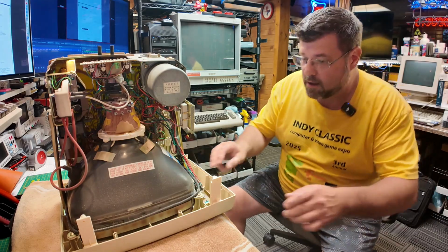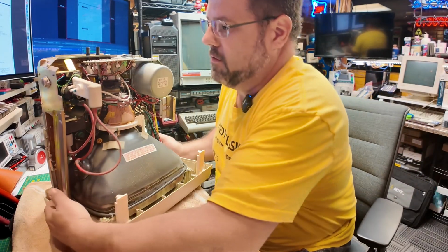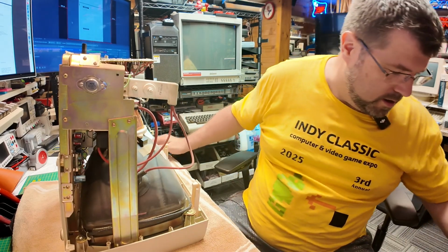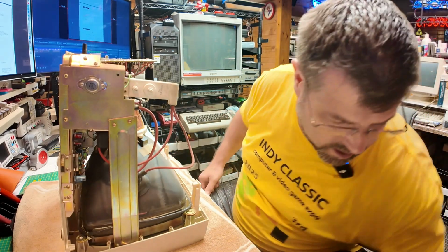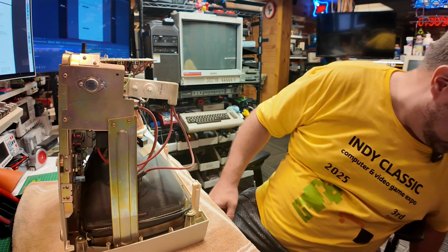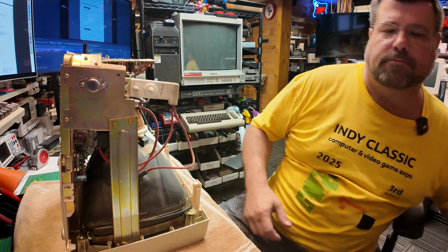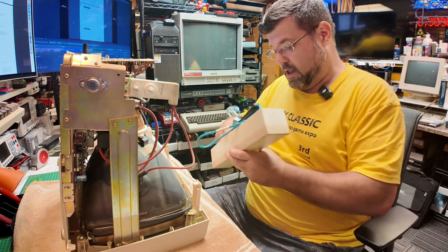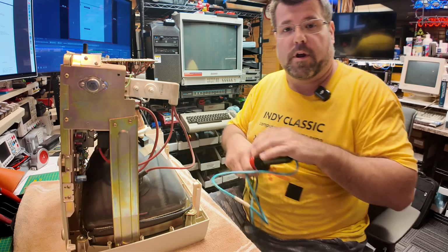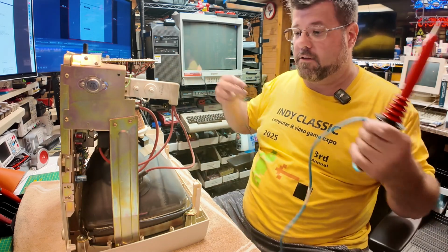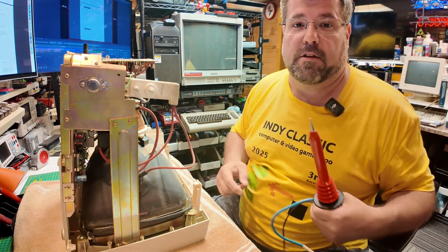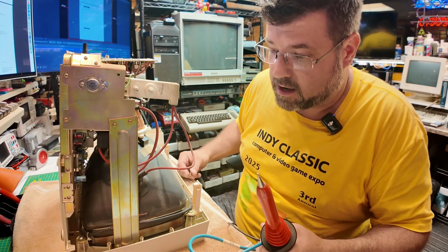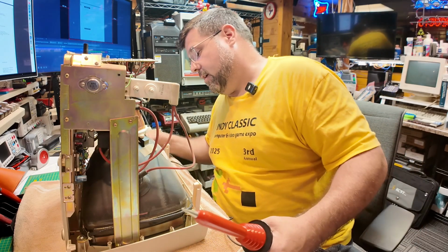So now, on these older monitors especially, some of the newer ones have built-in circuits to discharge the tube. These older ones, you have to be very careful. These tubes can hold a charge for quite some time. Now you can just use a screwdriver to do this, and incidentally, I'll give the age-old warning here. If you don't know what you're doing in electronics, the last place in the world you should be is inside of a CRT. So please don't get inside of a CRT without understanding what you're doing.